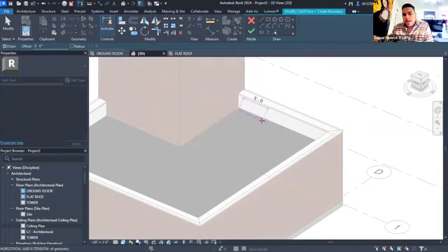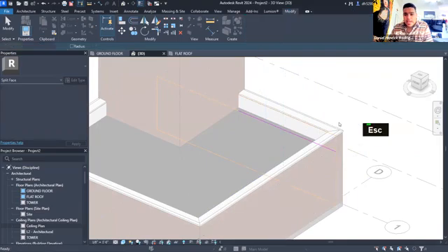And we want the parapet to be one material, and we want the bottom to be a different material, but they're all the same wall, right? When you click on it, it all has the same property. We're going to split the face, right? So we're going to click here, and we're going to follow the dotted line until it hits. Hit escape. Now we have the division, and I'm just going to hit enter.